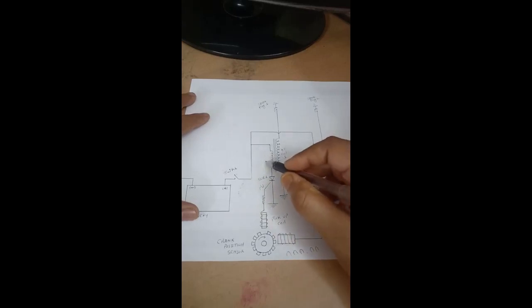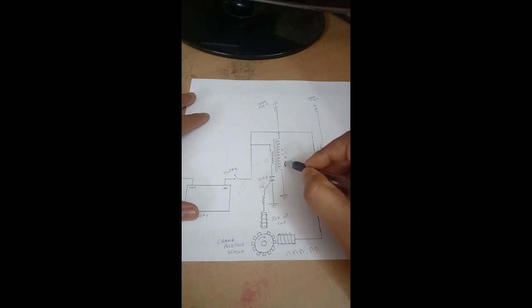So there is a change in the magnetic field in the primary circuit, and so there is a change in the magnetic field in the secondary coil. As it is a step up transformer, a small change in the primary produces a big change in the secondary. So whenever there is a small change in voltage in the primary, there is a huge change in voltage in the secondary.